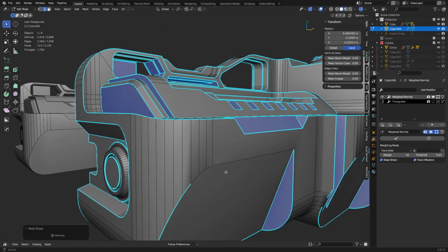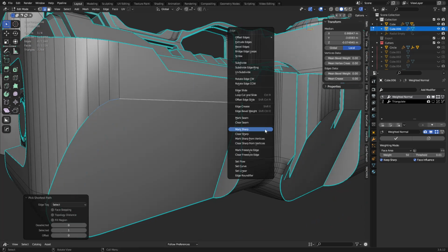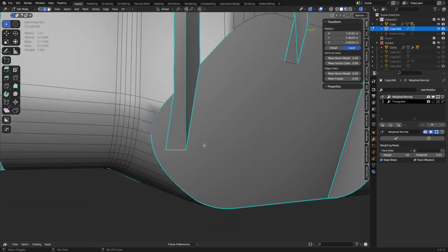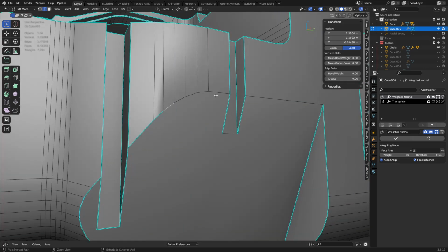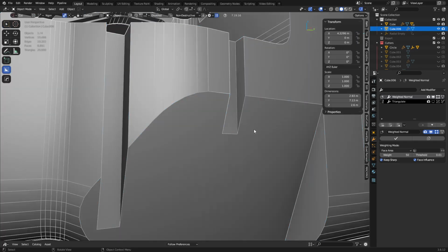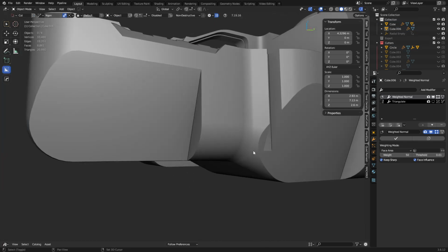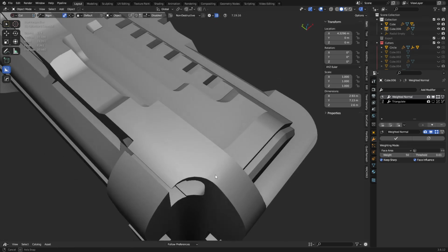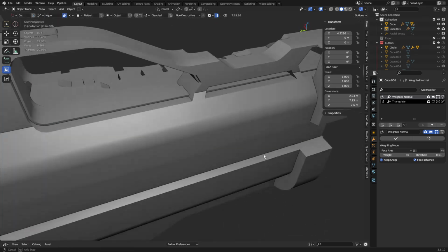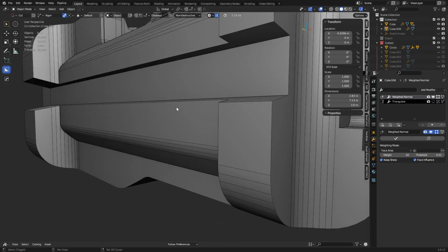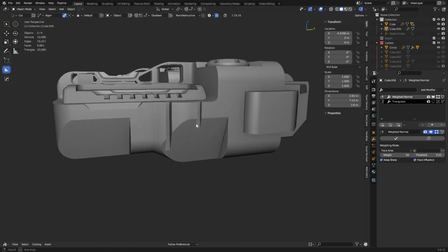Okay, so we're going to correct the shading first before we move on to doing UV maps. But you can see there's things that didn't get marked that should be. And so we'll go through real quick and mark, whoop, wrong one. Mark some of these as sharps. Going to fix up that shading just a little bit there in those cases. And usually if it shades badly, it means you don't have enough geometry or you'll have to use a sharp edge somewhere, maybe rework the topology a bit, but you can see it should look something like so with hard edges.